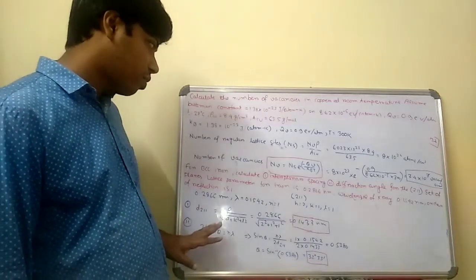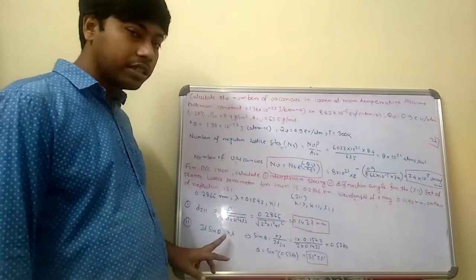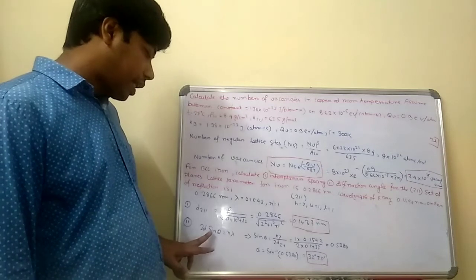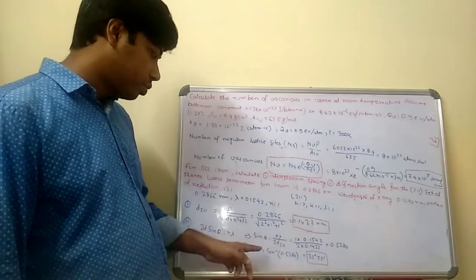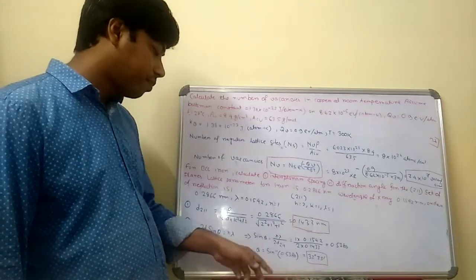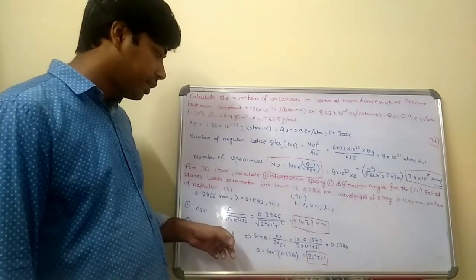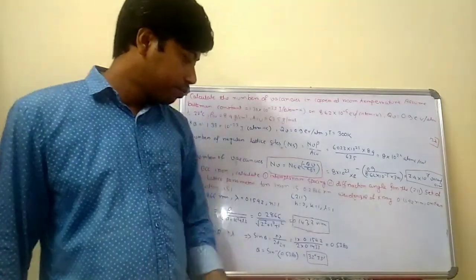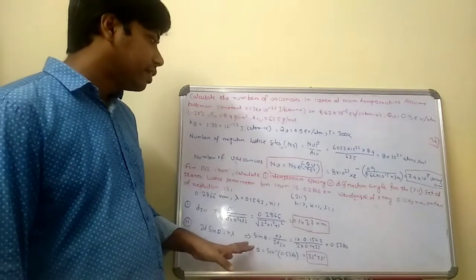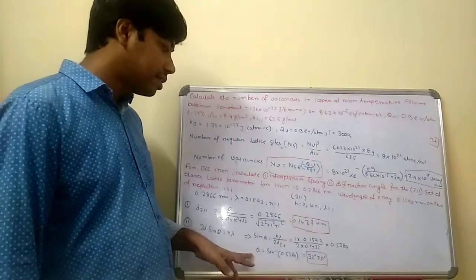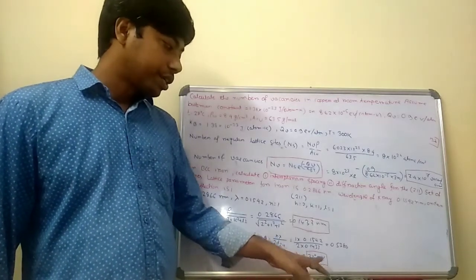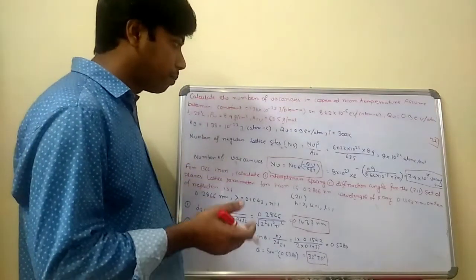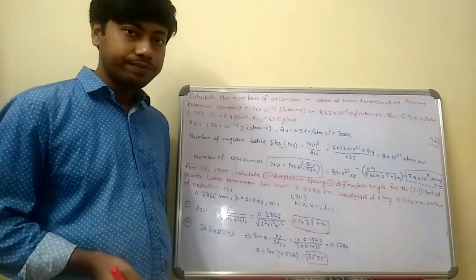And for Bragg's law, as you know, 2d sin theta is equal to n lambda, and you know the value of d, here d211, the interplanar distance for the plane 211, and n is 1 and lambda, the wavelength, is given. If you put all these values, then you can get the diffraction angle theta, that will be 32 degree 33 minute. So these are the interplanar spacing and the diffraction angle for the plane 211.